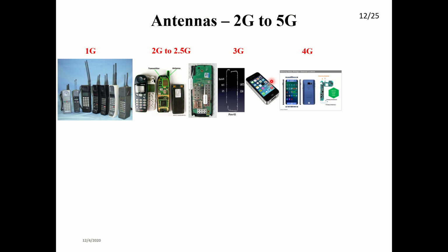So multiple frequencies have been implemented in 4G. Also in 4G, MIMO comes into picture, and MIMO means you will have multiple antennas and correlation between them. So many things are there. It has to work independently, and you have to have good isolation, with multiple bands also. So that was the challenge we faced in 4G antennas.